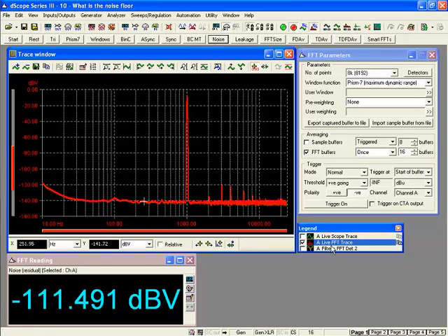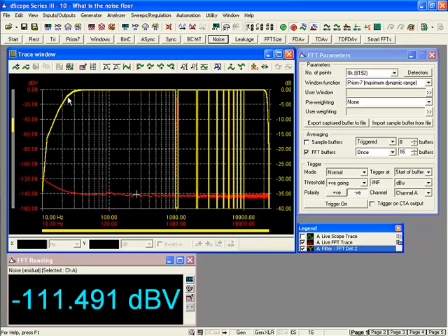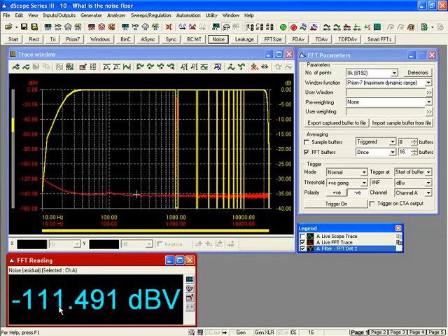So in other words, if we want to measure the noise over the range, let's say 20 Hertz to 20 kilohertz, what we have to do is, well, first of all, remove the fundamental and all of the harmonic distortion products using this perfect brick wall notch filter or series of brick wall notch filters, but then we must integrate the remaining energy over these other frequency regions, and when we add up all of those contributions, the result is here, minus 111 dBV, not the minus 140 that we may have thought was the correct answer.